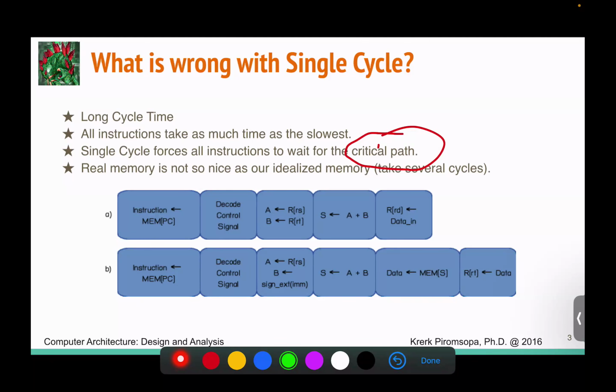The slowest operation that you have to pass through most components, and that's the thing that tells you how fast our clock can be. When you calculate the critical path you get one number, and that number means you must not use a clock faster than this. That's the idea from last week, the last few slides. We do the critical path and then we come up with some cycle time.